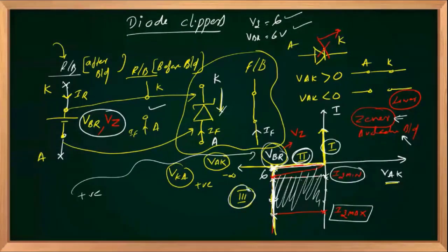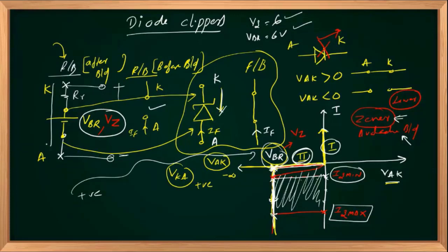If the Zener diode has a resistance RR present in the reverse breakdown mode, then the voltage between cathode and anode, with cathode positive in the reverse direction, will depend on the current flowing through the diode in the reverse direction.